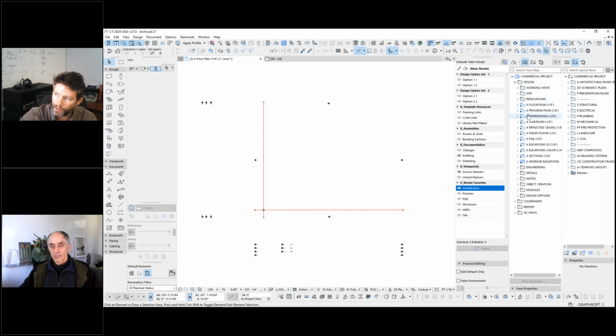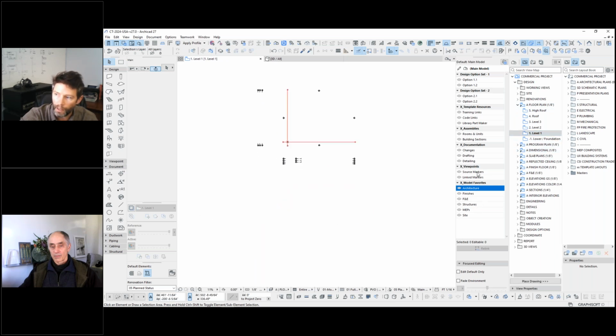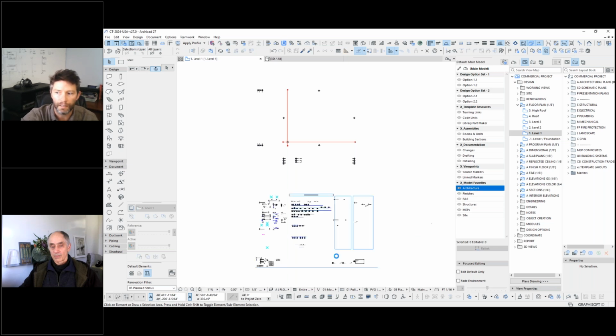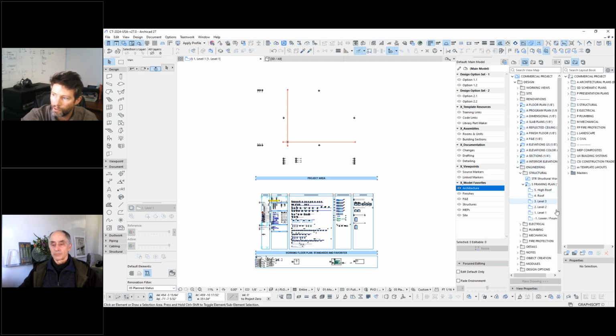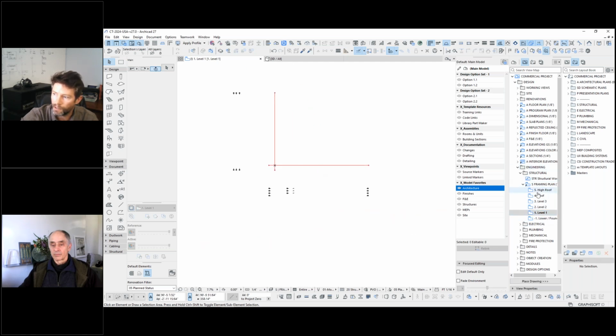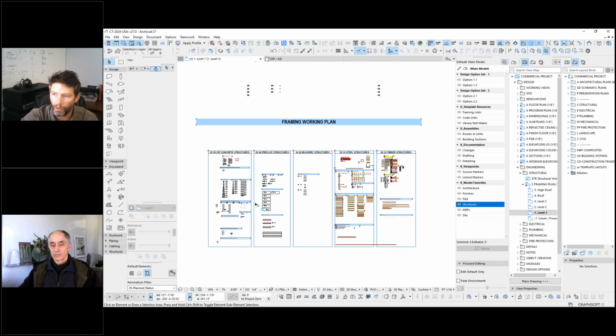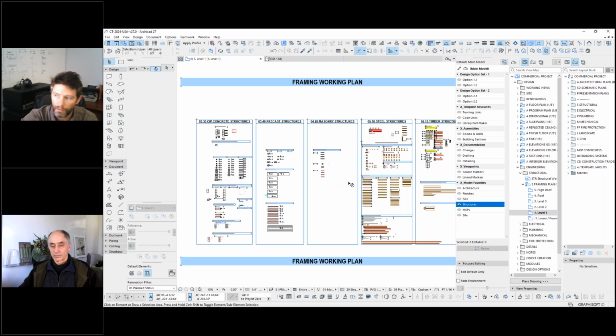But what I like about this is that we can be on any floor plan working type view. And at any point in time, I can go in and just start checking these boxes and see all the favorites assigned to those. So if we're on a different trade, say under some of our engineering views, like our structural framing, this is a layout type view where it doesn't automatically have it turned on, but we can just check these eyeballs and pull in all of our framing content.